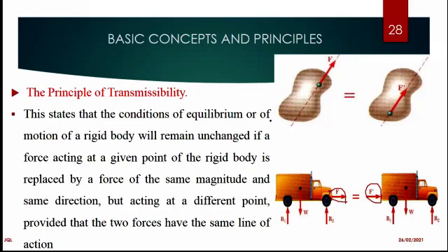Also here, this is just a body. It has been applied at point A with the same force F. It will give you a reaction equal to when you apply the force at any point, even here, for as long as it is along the line of application. Same force, the same magnitude, and you are applying it on the same line of application.